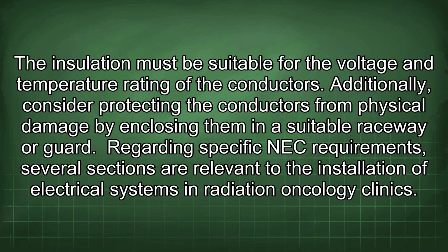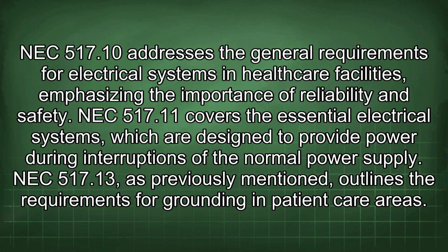Regarding specific NEC requirements, several sections are relevant to the installation of electrical systems in radiation oncology clinics. NEC 517.10 addresses the general requirements for electrical systems in healthcare facilities, emphasizing the importance of reliability and safety. NEC 517.11 covers the essential electrical systems, which are designed to provide power during interruptions of the normal power supply. NEC 517.13, as previously mentioned, outlines the requirements for grounding in patient care areas.